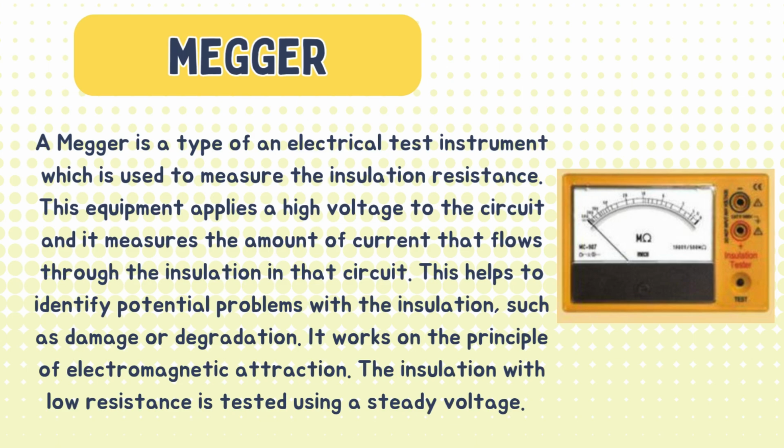Now, a Megger is a type of electrical test instrument which is used to measure the insulation resistance. This equipment applies a high voltage to the circuit and it measures the amount of current that flows through the insulation in that circuit. This helps to identify potential problems with the insulation, such as damage or degradation. It works on the principle of electromagnetic attraction.